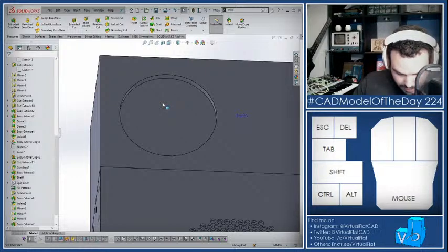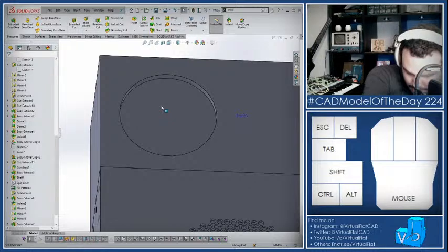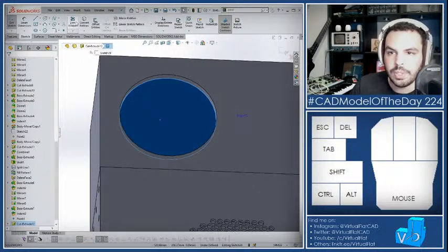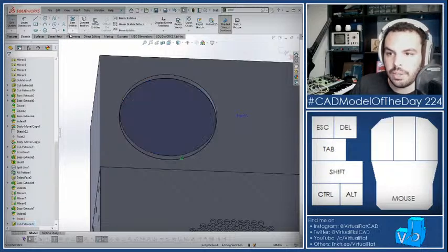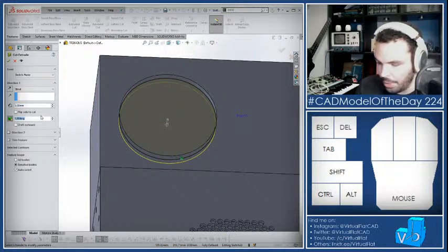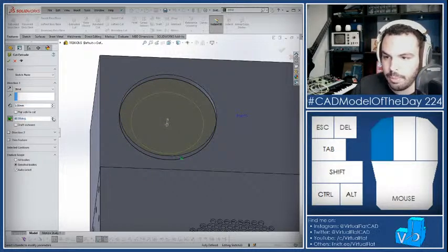I wonder if I can draft that into a conical face. Yeah, not really. Well, actually, what I can do is say convert, extrude, and just put a really gnarly draft on it, like 60. No, more still. And that inner thing is pretty small. Yeah, whatever.